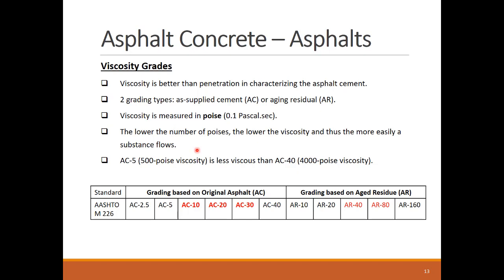The AR grading system is an attempt to simulate asphalt binder properties after it undergoes a typical HMA manufacturing process, and thus it should be more representative of how asphalt binder behaves in HMA pavements.